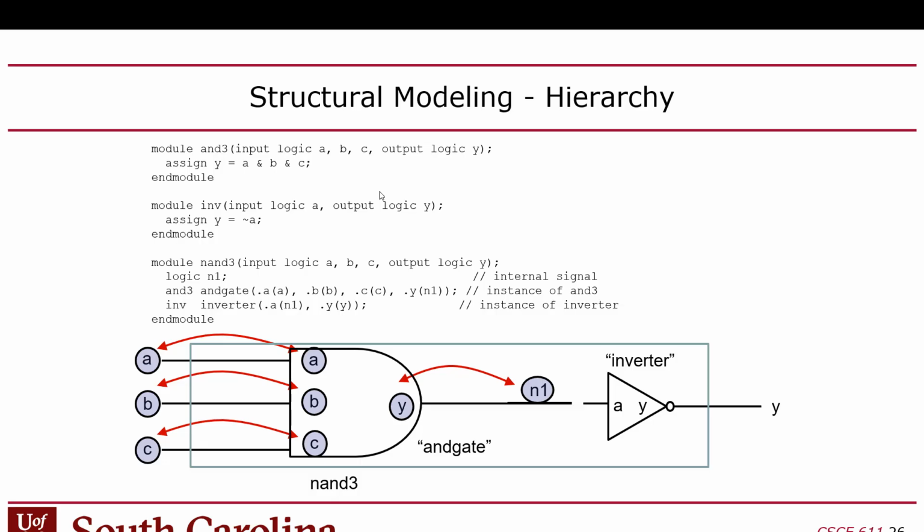And then again, if you use the same wire name in two different places, they're shorted, right? It follows the same rules that SPICE does, like you might have used in electrical 221, 222. So this N1, notice, is referenced here and is referenced here. The reason is because I'm plugging these two modules in. I'm plugging the output of this into the input of this. And that plug is established just through the name N1, right?